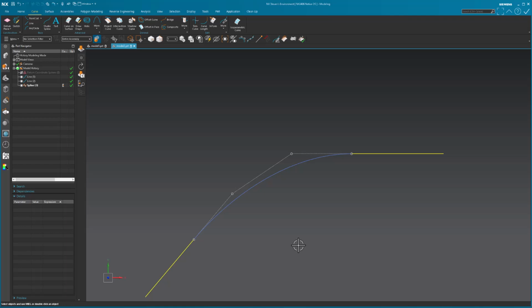For years, all I've heard is you got to use super advanced curves for all these crazy shapes and blah, blah, blah. I've used conics, little third order, 2-degree curves on exterior panels for primary surfaces, for lots and lots of things over the years. I didn't have to accelerate the edges. I didn't have to do this. I didn't have to do that. Because you don't have to, right? The blending can take care of all that for you. And people say, no, it doesn't work that way. Yeah, it does work that way, right? It's just people want to get fanciful with their methods and techniques, and whatever works for you, great, works for you. I don't care. But I'm telling you what I've done and what's worked for me.